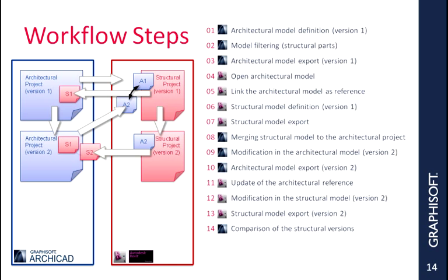14. The new IFC file received in ArchiCAD can be compared with the previous structural version. The result of the comparison is listed before merging it into the current running architectural project. 15. The comparison process automatically merges the detected changes only, so the new, modified, and deleted elements will be inserted into the architect's running project as a reference.